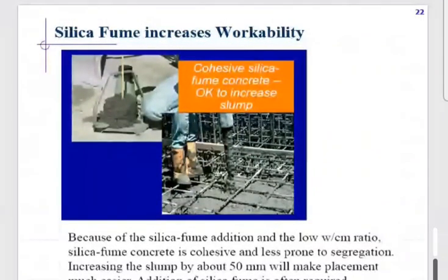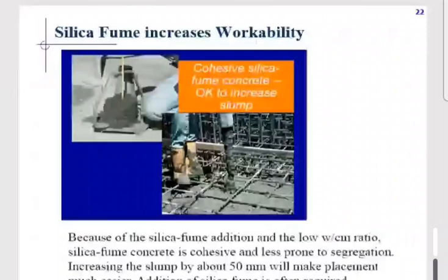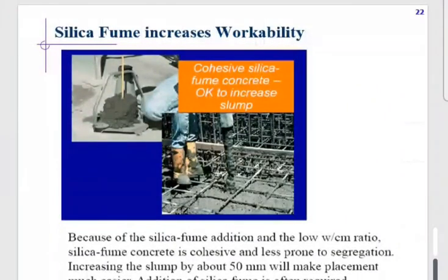So there are different kinds of silica fume. Well, I have worked on this in my PhD. During my PhD, I worked on 6 different types of silica fumes. Few of them were complementing the slump, and few were there which were actually drastically reducing the slump.